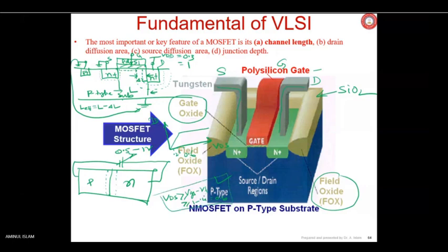In case of a MOSFET, before that it is in linear region, current is linearly increasing. After that, current becomes flat, parallel with the x-axis. This is the case of a long channel MOSFET, very big, 20,000 nanometer. Earlier channel length L was 20,000 nanometer or 20 micrometer, say around the 80s. Nowadays it is even less than 20 nanometer. So what is happening is, due to depletion layer, effective channel is getting reduced and current is now increasing with the VDS. This is not a good sign, not desirable.